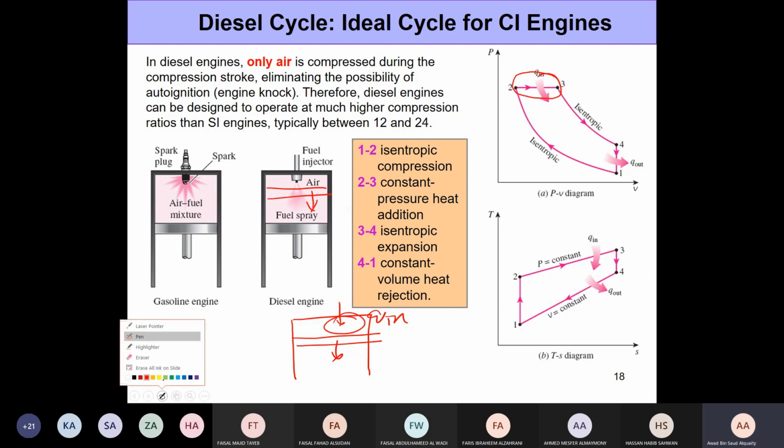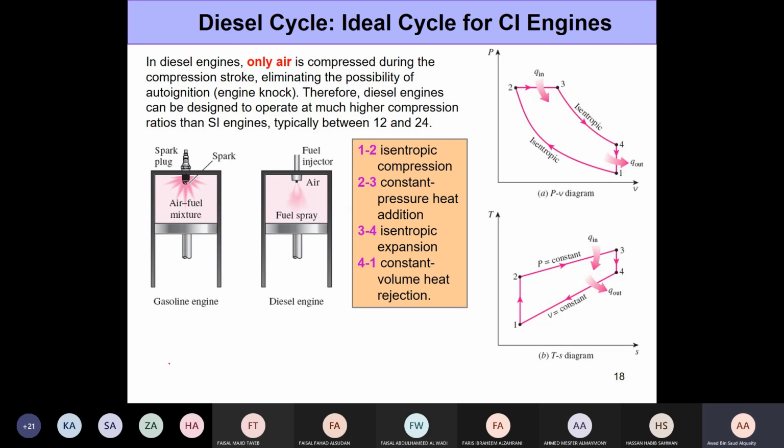So this is the main difference between a petrol and a diesel engine, or gasoline and a diesel engine. Now, certainly, since we are having heat addition at constant pressure, we know that when we are adding heat at constant pressure in a free moving piston sort of assembly, boundary work is being done as the piston moves down, right?